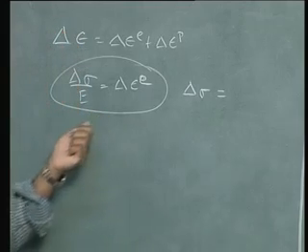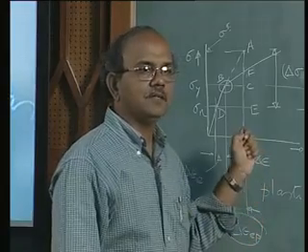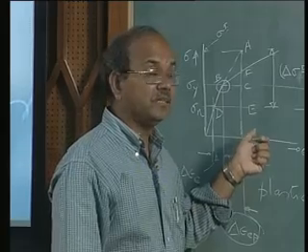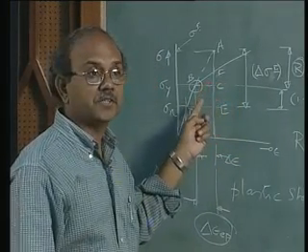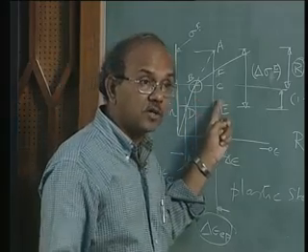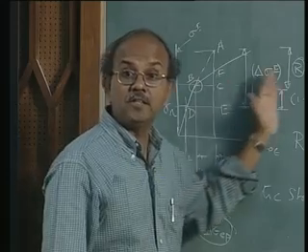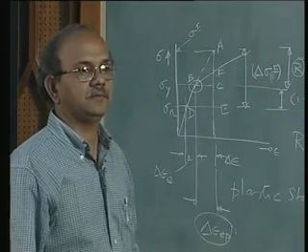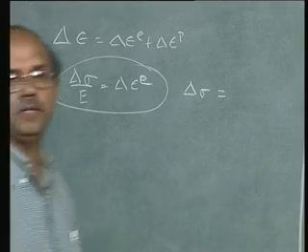That brings us to a comment. I think maybe you know it, but it's very important to comment because people usually get confused about the increase in elastic strain in the plastic region also. Please understand that elastic strains do not stop growing when you reach yield, but keep on increasing even in the elastoplastic region. What does that physically mean? Fantastic question. So what does this physically mean?